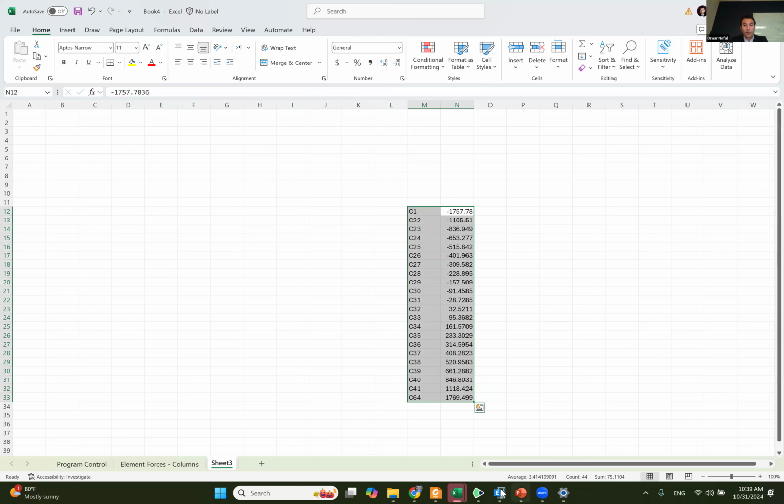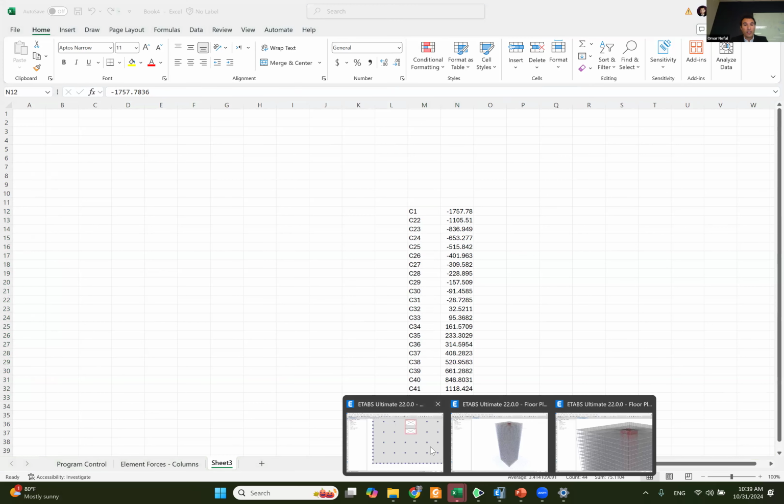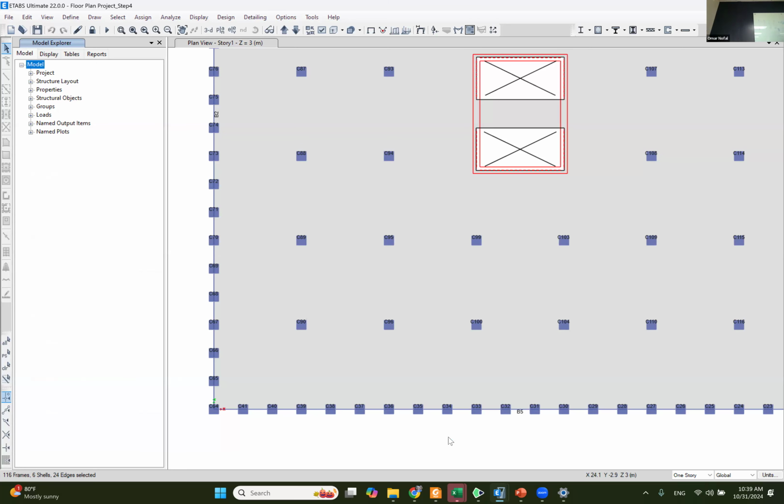By the way, let me ask you, which edge did we pick? This is earthquake X going this way. And we picked this side. How's the shear line supposed to look like? Is that the one that makes like this or the one that makes like this? That's the one that has the stresses, tension, and then 0, 0, 0 until it goes compression, right? So that's how it's supposed to be. But this one is supposed to be all tension, right? Okay, so let's see when we plot this, how it's gonna look like.